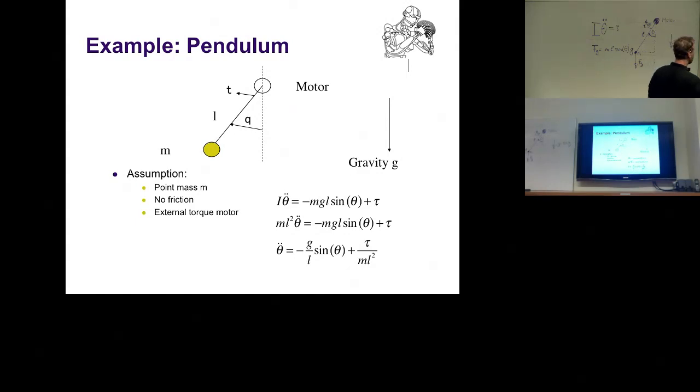And we have to agree on the sign. Now, so gravity right now is pointing down. So it's trying to push the pendulum back. So against what we defined as a positive torque. So we need to put a negative sign in front of it. Okay? So we can now complete these equations and basically write here minus MLG sine theta. All right, we have that. Cool, and that's exactly the same equation that's here. Just wanted to tell you where it comes from.